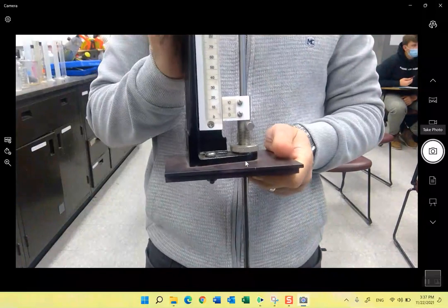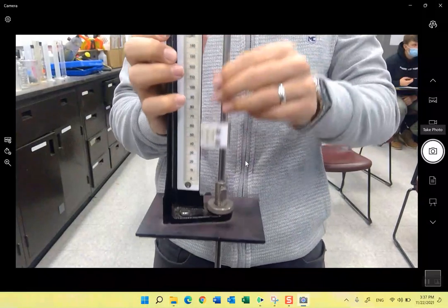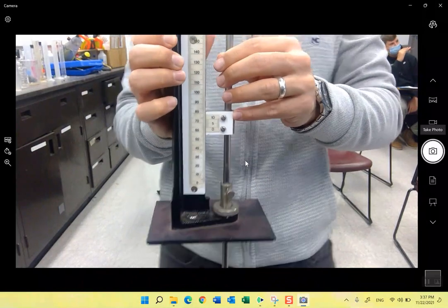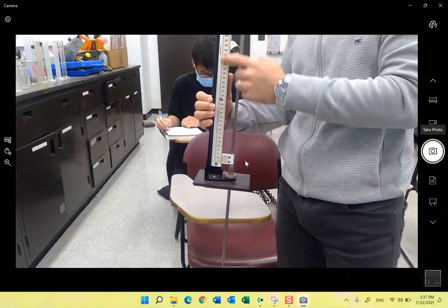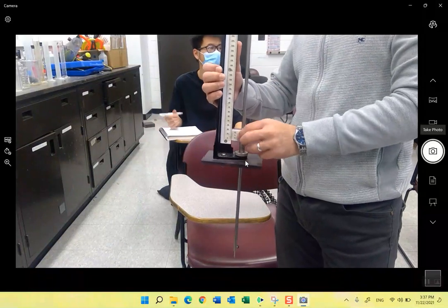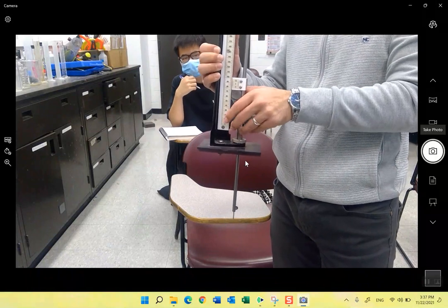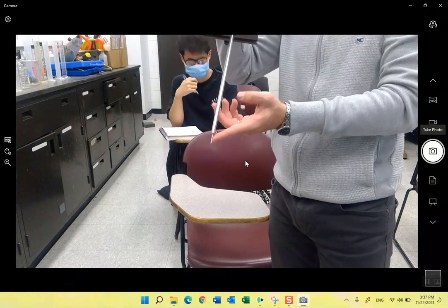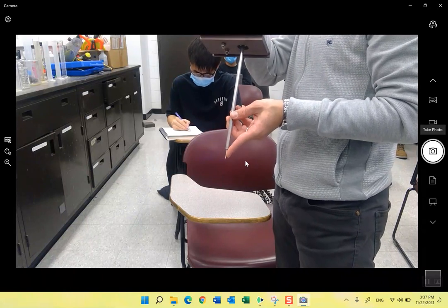Okay, so the point gauge consists of different components. It has this slider ruler. It's a very small ruler, and it has this fixed ruler that does not slide, and we have this screw that can hold the slider from falling down when it's locked, and of course we have this point that will be inserted or should coincide with the water surface.